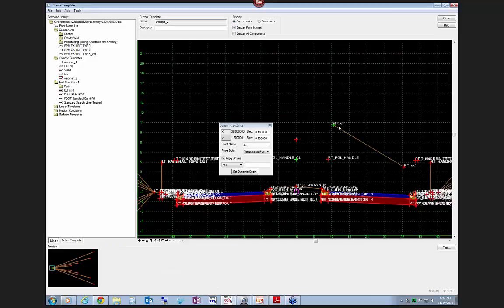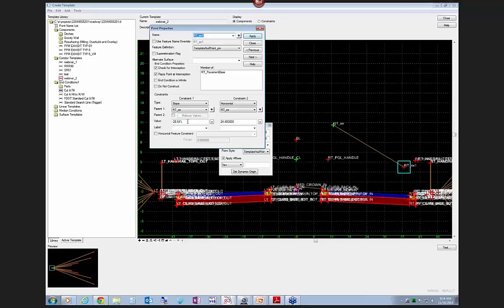So now this line is, if I look at the point properties here, it's actually at a negative 26.64%, 24 feet. Well, that's not a standard slope or standard width. So I could change this to say -1/4, or I could have used an exact key in here with this key in dialog, and I can show you that in a second too. I'm going to set this to 25 feet and choose apply, and now it's going to modify that.